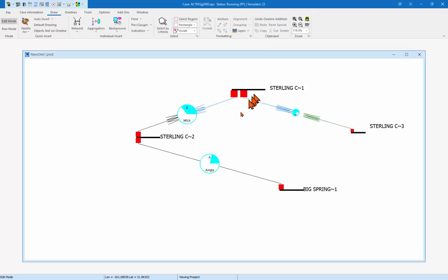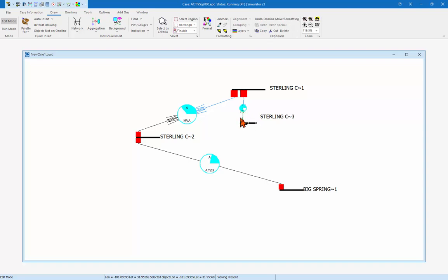And so what that does is it just draws any transmission lines or transformers that exist between the buses that are on the one line diagram. And I can see I have a couple of transformers right here. If I want to reposition those, I can just click and drag. And the line, this is called anchoring. The line will basically stay anchored to the bus that it's connected to.